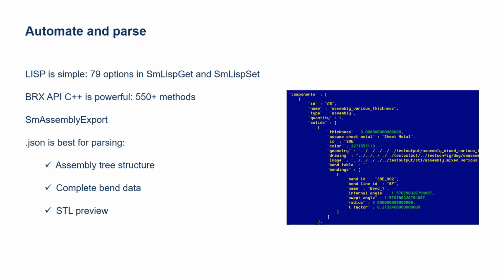And finally, let's mention more automation possibilities. So for some smaller scenarios, there is a Lisp API, and BricsCAD Sheet Metal API gives you the power to implement or customize your own sheet metal application on top of BricsCAD. So literally, you can implement your own sheet metal. And if you want something simpler, but still in an automated context, you can continue with assembly expert, which does batch processing. A noticeable enhancement of this command is that it now delivers easy to parse JSON output, which is very detailed. And so your automation scenario can run assembly expert and then interpret JSON after it.